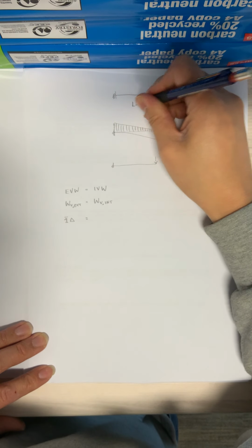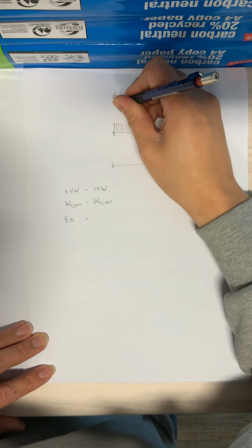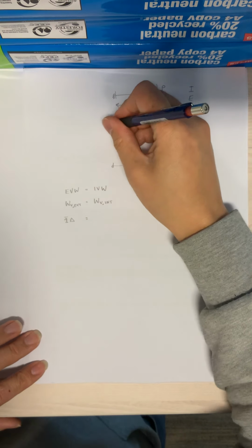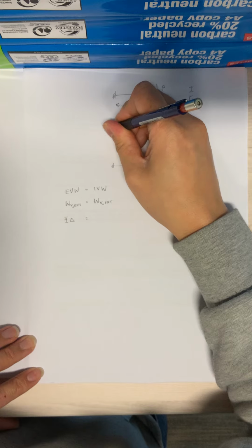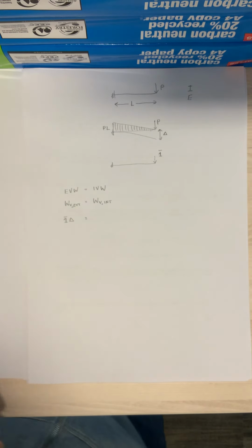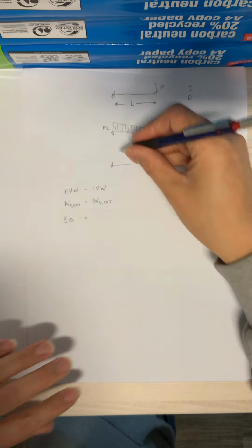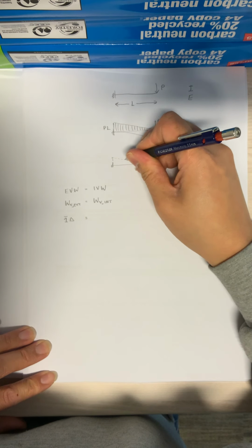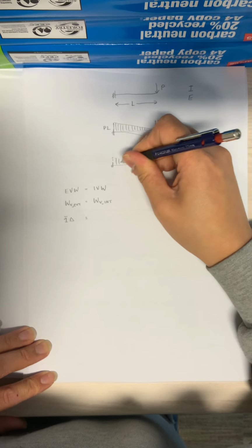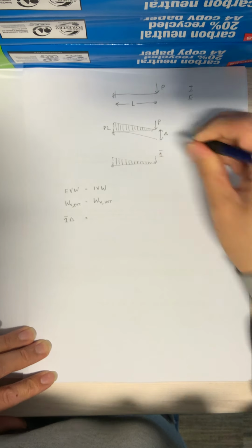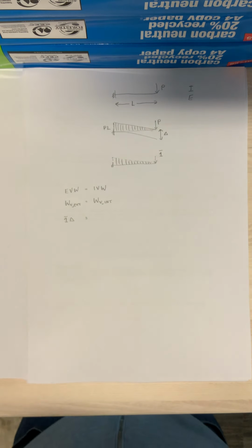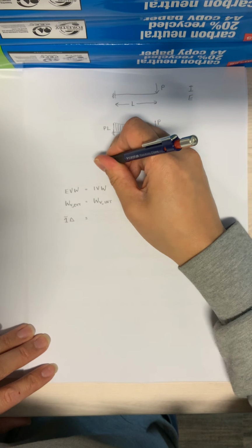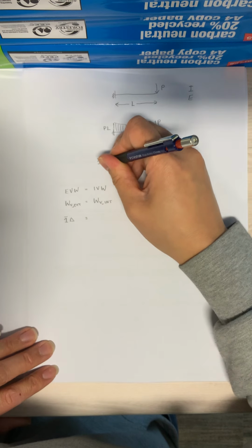And then we'll say that's the length of the system here. So I'm trying to derive an equation, basically. The bending moment here at the end is going to be PL, since P times the distance there. And under the 1 bar, the shape of the bending moment diagram is going to be the same for the virtual. So that's the real and that's the virtual. And the magnitude of the bending moment is going to be 1 bar multiplied by L, of course.